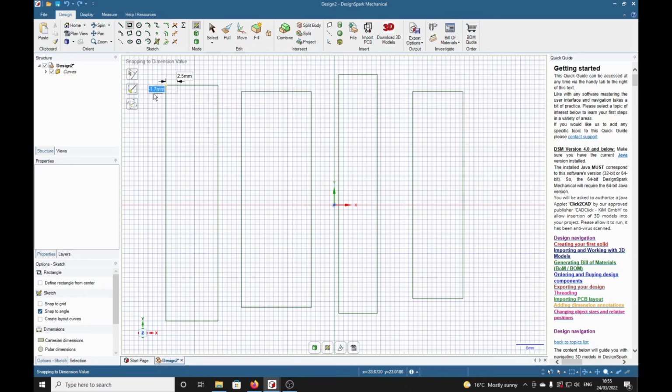There's a negative sign there, see? So if we want that also 2.5, we type minus 2.5, and that finishes it by typing the return key. Now don't press any buttons on your mouse, but just drag the mouse. Now you've got another rectangle you can put in, and you can type in whatever dimensions you require for that.